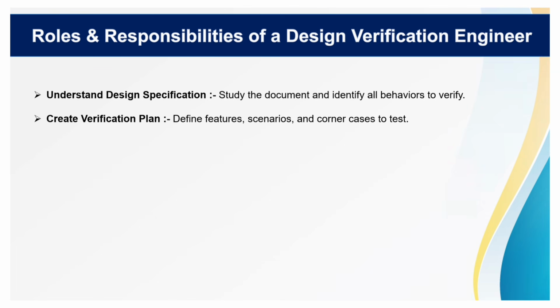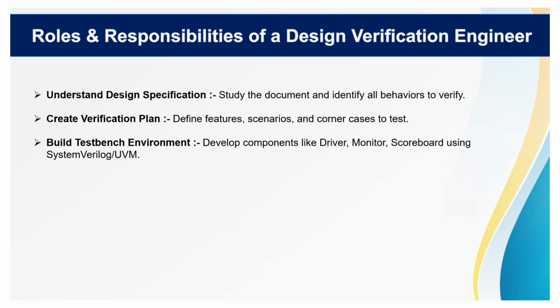After that, the DV engineer builds the testbench environment. This environment interacts with the RTL design and helps check whether the output produced by the design is correct. Typically, the environment includes components like driver, monitor, scoreboard, and stimulus generator, usually written using SystemVerilog and verification methodologies like UVM.